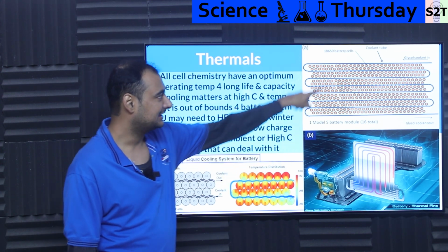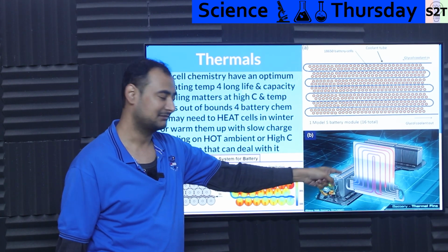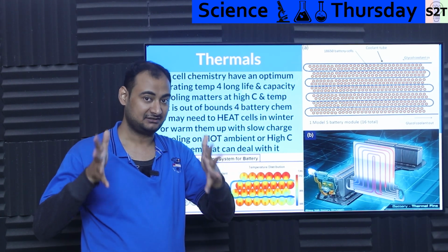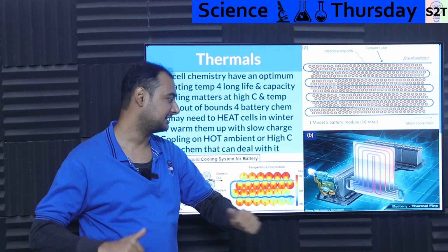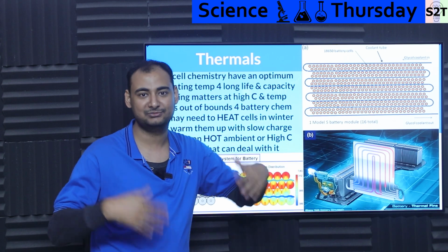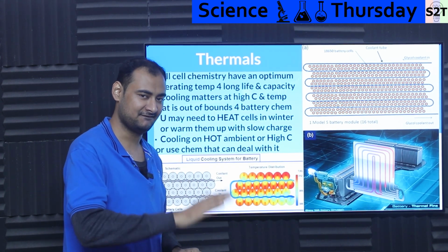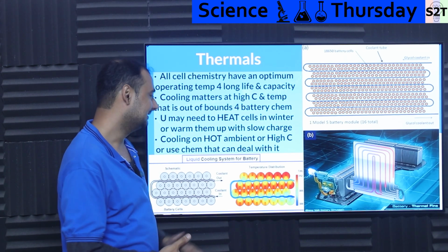So this is the system that Tesla uses, and this was a system from a bankrupt company. You tell me which company was that? They were making large prismatic cells, very good current capacity and all that jazz, but they did require a flat plate heat exchanger between each cell to make sure that temperature remains okay-ish, especially when you're flooring it. So these are the thermal aspects.